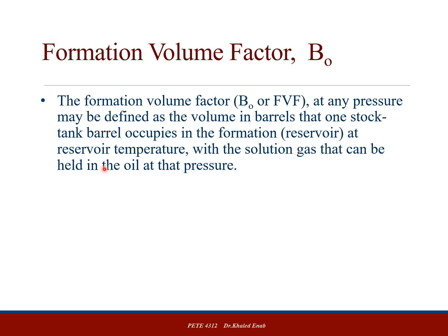So from knowing the Rs, I can know how much gas will be released, right? And then the amount left from this oil, plus how much it expands, because the liquid expands as well with lowering the pressure. It's not a lot of expansion such as in the gas case, but it expands to a degree. When it's moved to the surface condition, that left amount, when I divide it by the initial reservoir fluid plus the dissolved gas volume, that will be my formation volume factor.